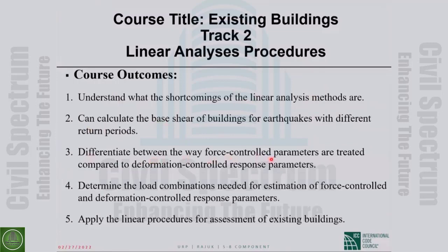We should know that for force control parameters, we use a load combination where the force control is divided by C1, C2, J. But for deformation control, we use another load combination, which is gravity load plus earthquake load. We don't divide by C1, C2, J, which is here, this one. And we should generally be able to apply the linear procedure to assess limits.